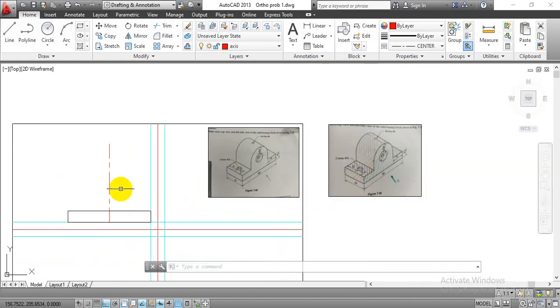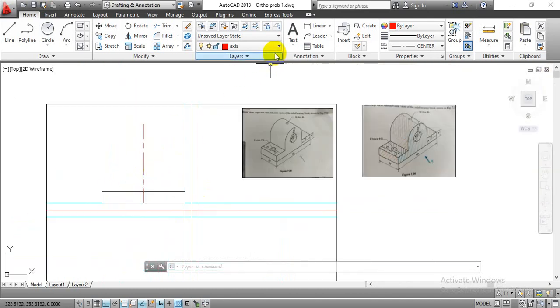So for our reference we can draw one line for the length equal to 30 with respect to this corner point. Okay, so just enter distance 30 over there and press enter button. Again press escape button to come out of this selected line.